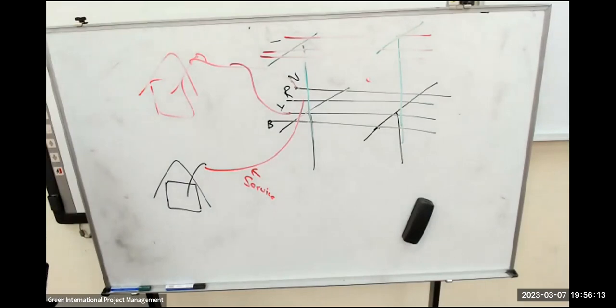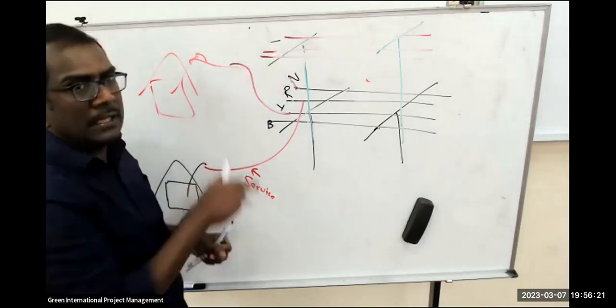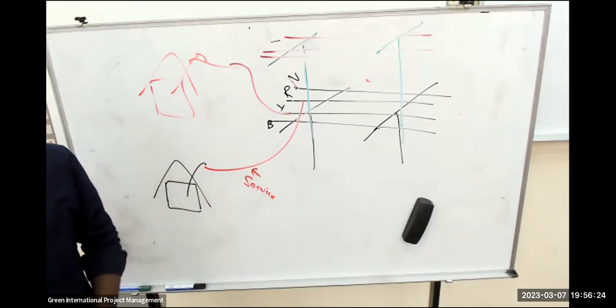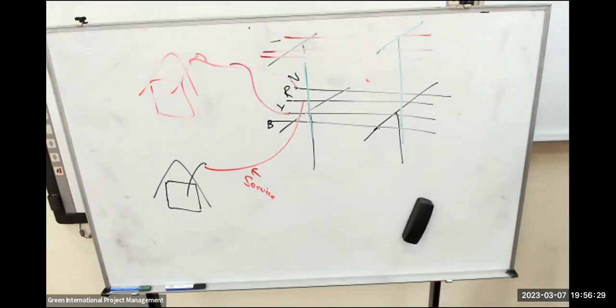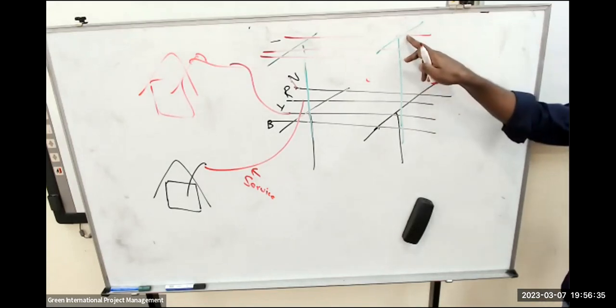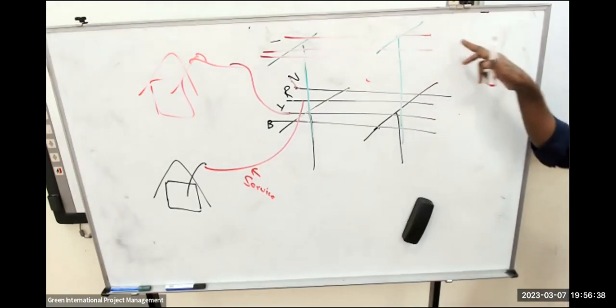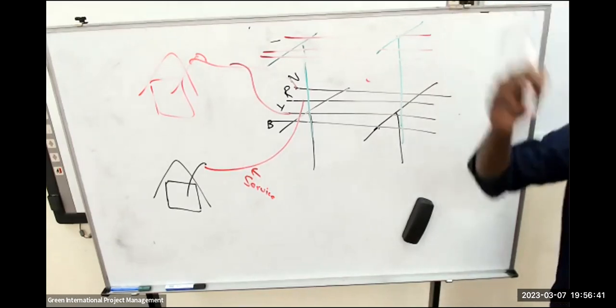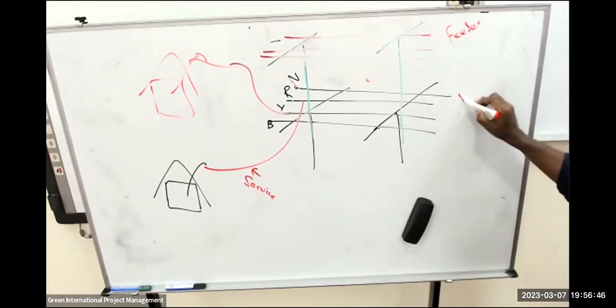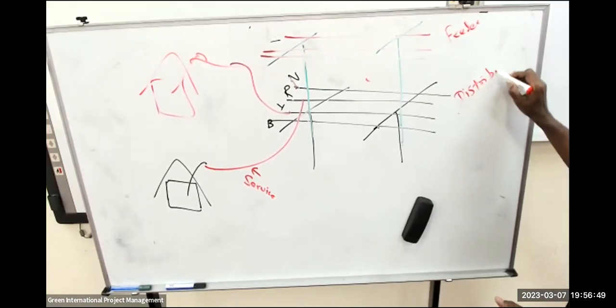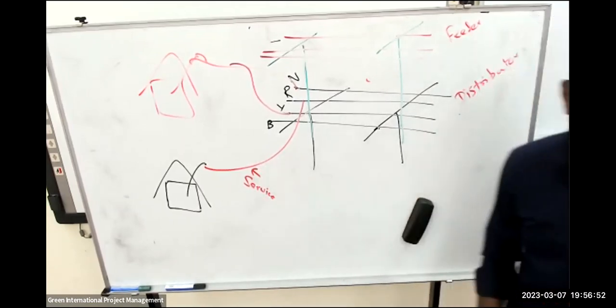So again, imagine you go to your home country, near the house, we have a pole, we have two lines on the cross arms. In the top cross arm, we have three wires. In the bottom, we have four wires. And see these three wires, if you enter the first street and go to the next street, all three wires go to the next street transformer. So all these wires are feeders, this we call feeders. All the feeders are connected to the main transformers. So this wire we call a feeder. This wire we call a distributor. And this wire we call a service line.